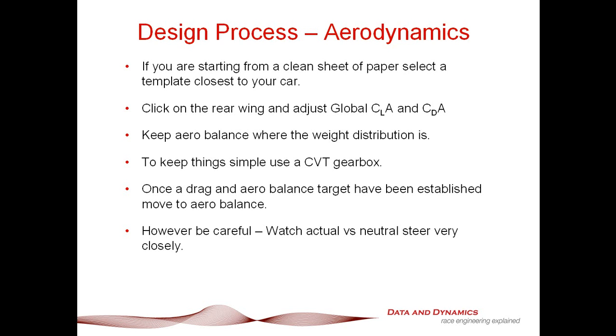If you're using a GT3 car, we've got an LP560 template, so I would use that as a start point. If you're designing any sort of high downforce car, either an open wheeler or a sports car, I would strongly suggest you start with the GP2 template, because you're going to get an idea of what the pitch sensitivities are going to do.